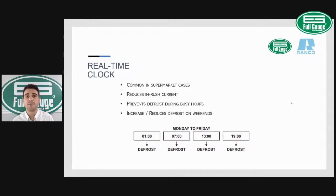Another nice feature about the real-time clock defrost is the possibility to set weekly and weekend defrost cycles. For example, a refrigerated warehouse that does not work on the weekends won't have door opening and closing. So it is likely that you can reduce your defrost cycles from 6 to 4 defrosts a day, for example. So the real-time clock defrost provides you such flexibility to adapt the defrost to the most convenient time for it.